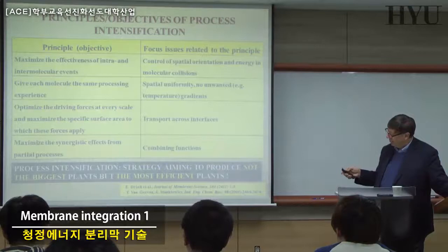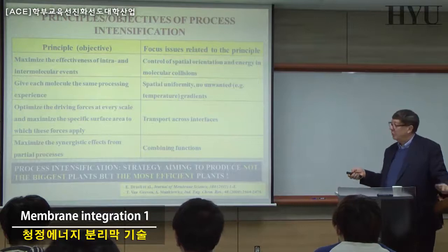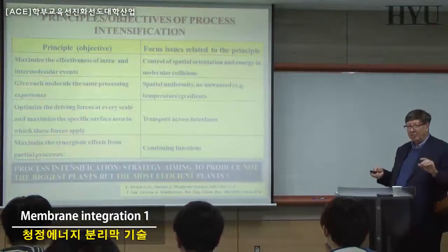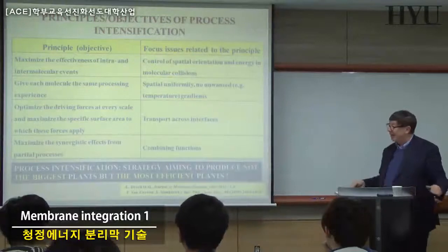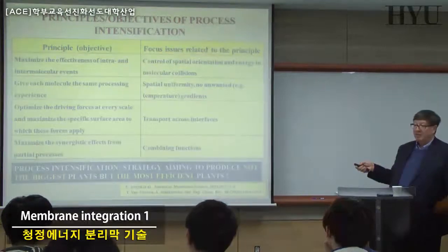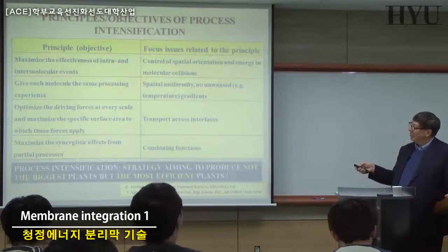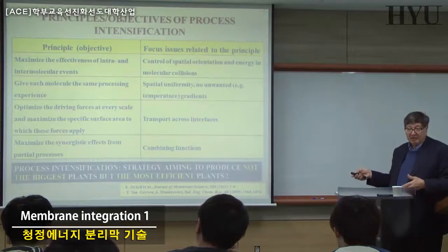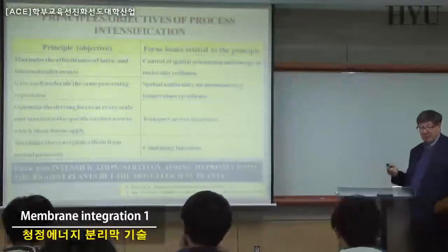We have to try to give the same level of efficiency at molecular level to each molecule that we are using, to avoid the problem of hotspots or deviation from the final result, etc. And that means, for example, that we have to focalize on space uniformity, the process to be the same at any level. So we want to avoid, for example, thermal temperature gradient, concentration gradient, or pressure gradient in different process, etc. Not easy, but has to be done.